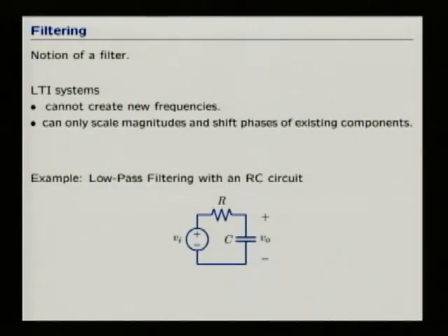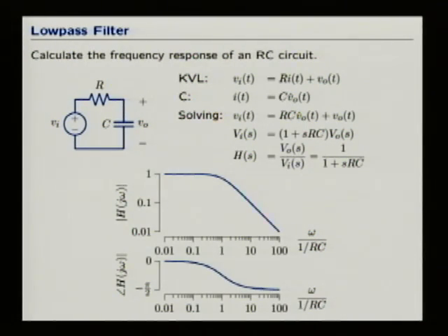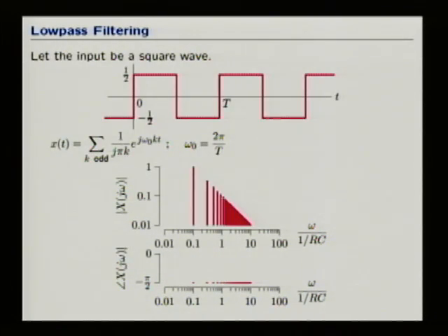So we already talked about a filter. I motivated a filter by thinking about Fourier series because it's easy. If you think about the system that's comprised of a resistor and a capacitor, and you have as an input VI and an output VO, then you can think about that system being a filter. The filter can be characterized by a frequency response. You're all experts at that. And if you can break the signal into Fourier components, which was easy when we had a Fourier series, then it's easy to calculate the output as the sum of weighted and possibly time-shifted versions of the components of the input.